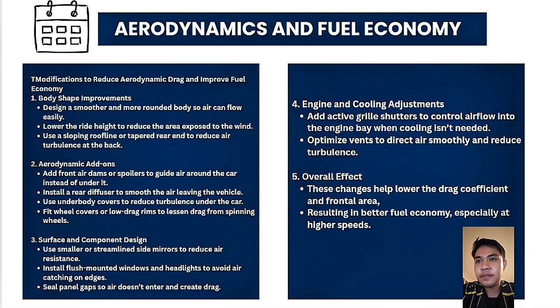Number 3, surface and component design. Use smaller or streamlined side mirrors to reduce air resistance. Install flush mounted windows and headlights to avoid air catching on edges. Seal panel gaps so air doesn't enter and create drag.